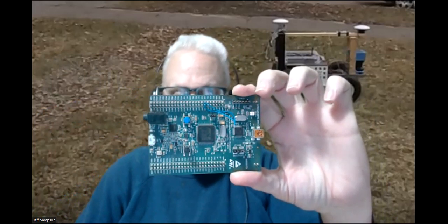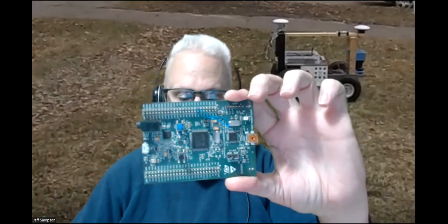And so if you've got a board like this, when you start your project, it says what kind of board do you have? You can say, oh, I've got an F4 Discovery board with this size of processor. And what it'll do, it pulls up a little chip that looks like this, so you can see all the pins around it. And then on the left, it says, here's all your peripherals. So to set it up, you just go to the left and say, I need a UART, I need a CAN bus, I need 4 timers, whatever it is.